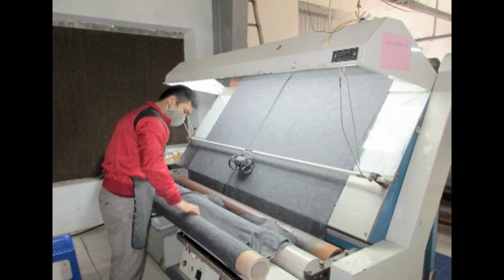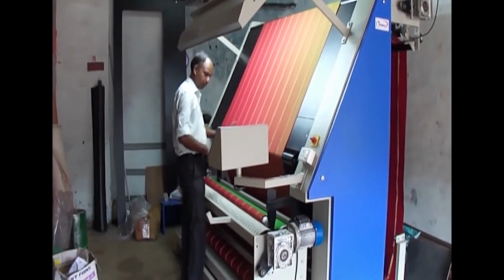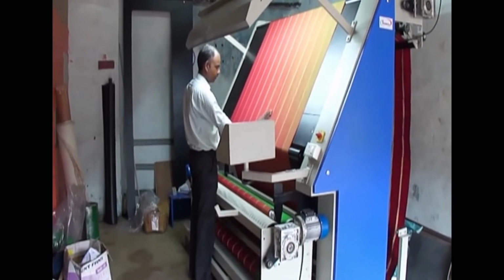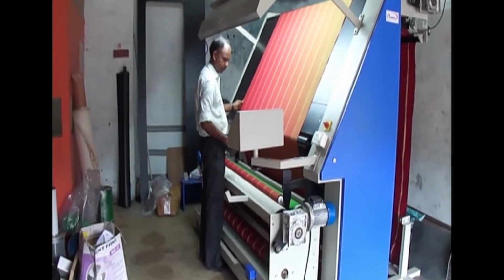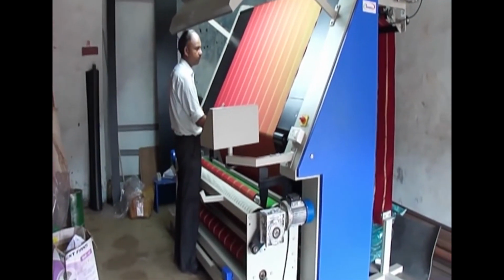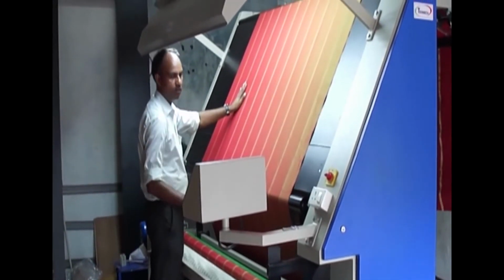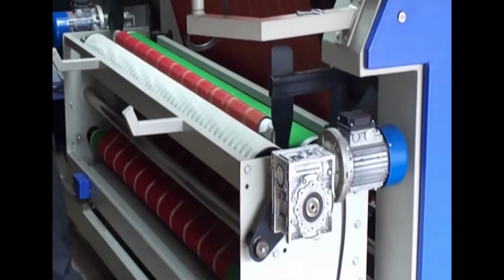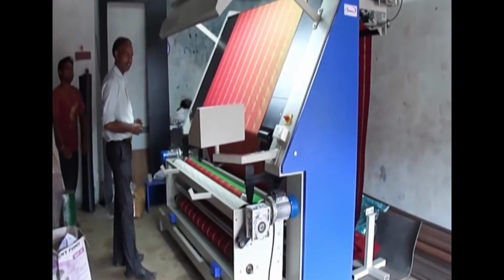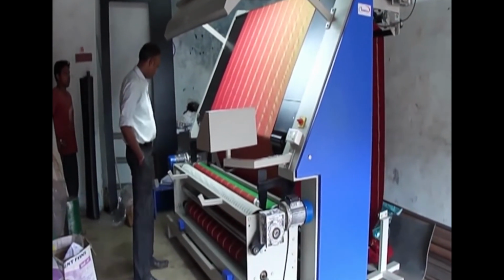It is done through fabric inspection machines, and these are very important for every industry. The machine consists of a perching platform and an overhead lighting system to view the defects. Fabric passing through the frame must be at a 45 to 60-degree angle to the inspector and must be viewed under appropriate cool white light, F96 fluorescent bulbs above the viewing area. The backlight can be used as and when needed. It is used only for a few fabrics. The fabric from the bolt is brought over the lighted platform with the help of rollers and is withdrawn after checking and rolled onto another bolt.